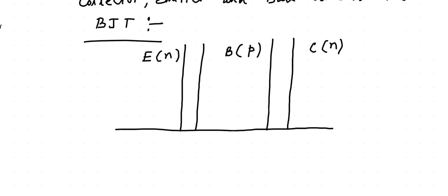Okay, so now in the forward active mode, we know that the base emitter junction is forward biased, right? And the base collector junction is reverse biased. So that is what we call forward active mode. Now I will show you the minority carrier concentrations in the different regions.